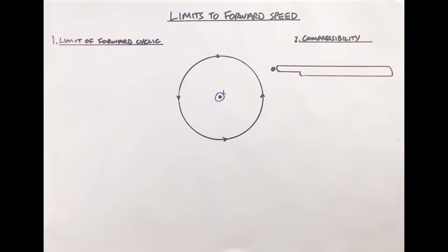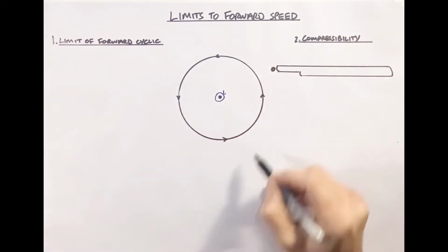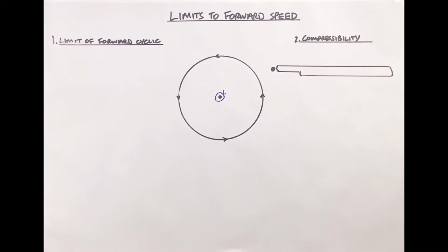So when we think about how many times it's rotating in a minute, 300 times, in that minute the tip is going to be moving at a much greater speed than the root. We can actually work that out sometimes, and for this demonstration, we'll just assume that the tip is creating an airflow of 400 knots.